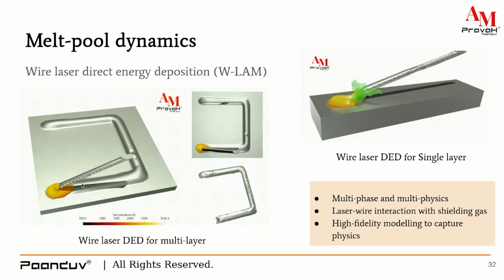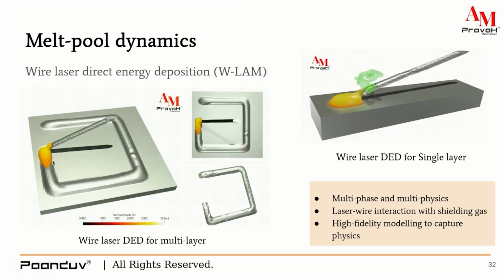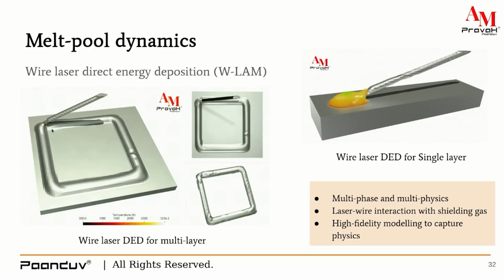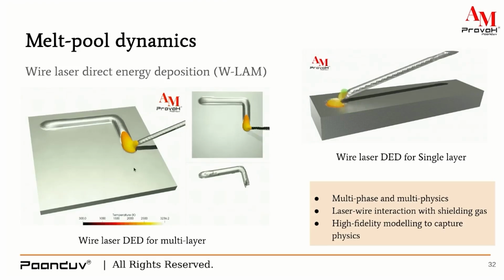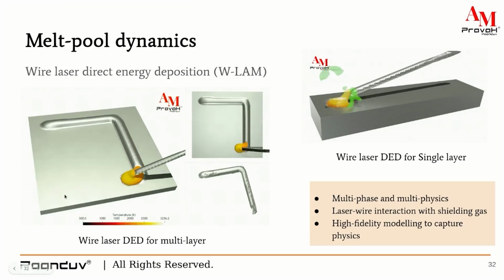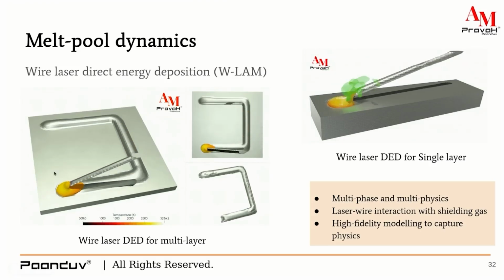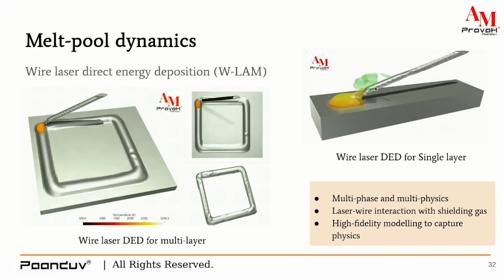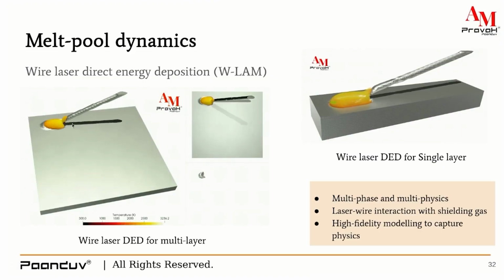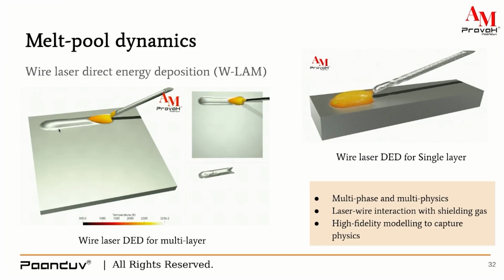These can be changed by different thermal experience to the material, and depending upon the solidification rate, these evolution processes can be changed. Now you know that in laser powder bed fusion we have temperature gradients ranging from 10 raised to power 6 to 10 raised to power 7 Kelvin per minute, and because of the rapid heating and solidification processes, these microstructures are evolved in these systems.